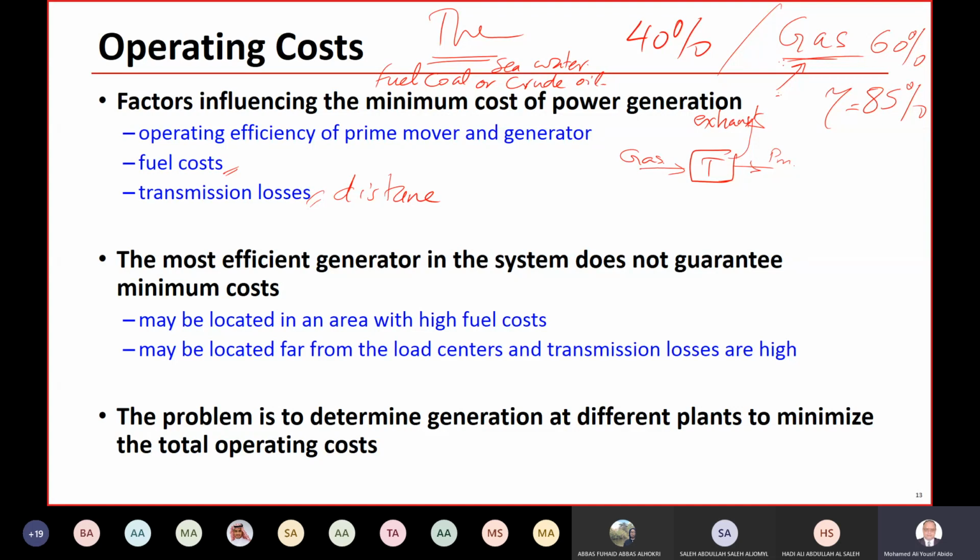But for the combined cycle, let us utilize this hot gas, which is the output from the turbine, in order to heat up some water. We can have another turbine and generator here, and this gas is considered as a fuel to generate steam, and to generate another part of electricity. So you have two outputs of electricity, right?